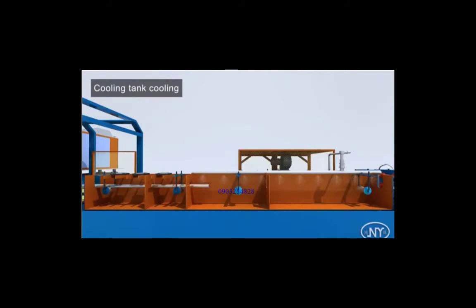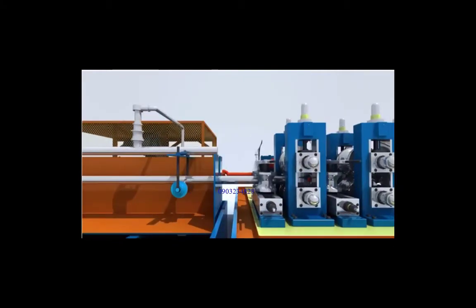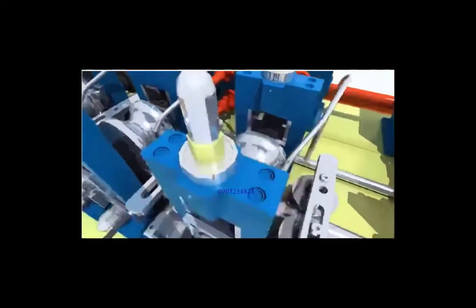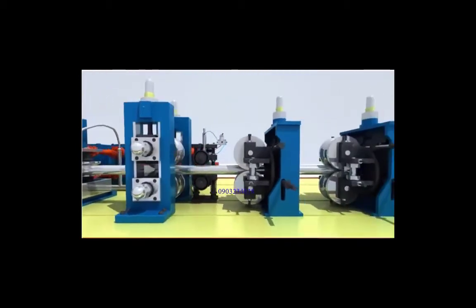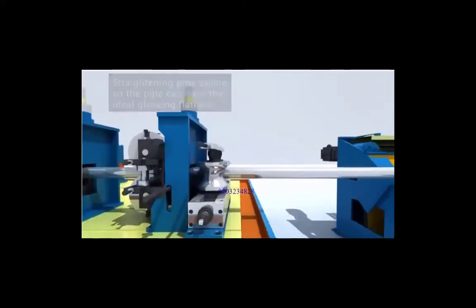The cooling tank is used to cool the welded pipe blank to the same temperature as the base material, so that the finished tube will not deform after being placed for a long time. The sizing machine is used to shape the welded tube after rough forming to achieve an ideal geometric size. It can change round pipe to square or rectangular by changing molds. The tail section is installed with 2 sets of straightening devices for online straightening.